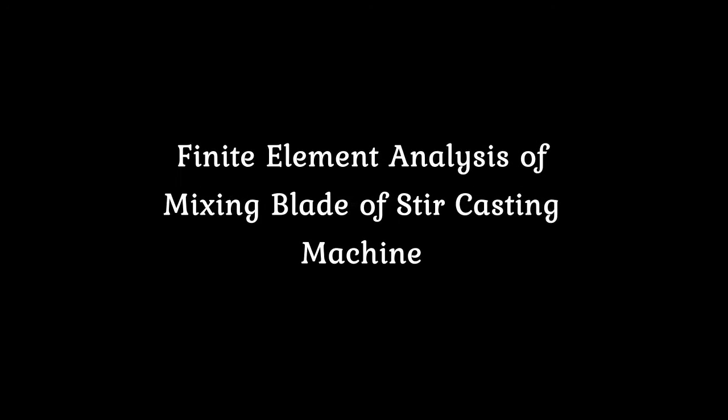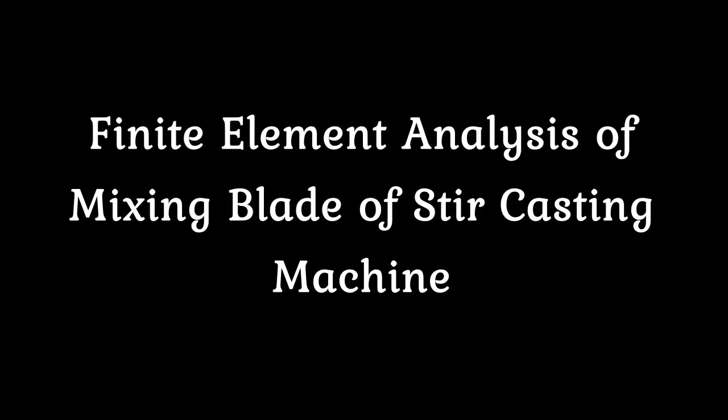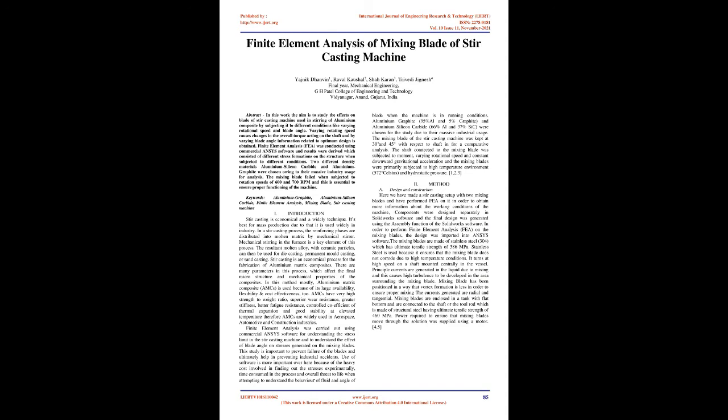Finite Element Analysis of Mixing Blade of Stir Casting Machine. Abstract. In this work the aim is to study the effects on the blade of a stir casting machine used in stirring of aluminium composite by subjecting it to different conditions like varying rotational speed and blade angle. Varying rotating speed causes changes in the overall torque acting on the shaft, and by varying blade angle, information related to optimum design is obtained.